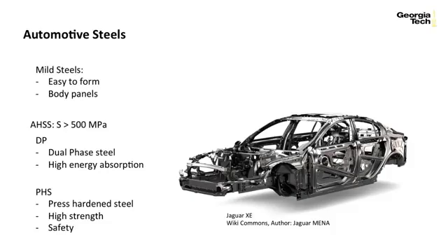It's quite complicated, the trade-offs between steel and aluminum in the automotive world. And keep in mind that while aluminum is lighter, if you can make the steel stronger, you can use less of it. So the strength-to-weight ratio is very dependent on the types of aluminum and the types of steel.